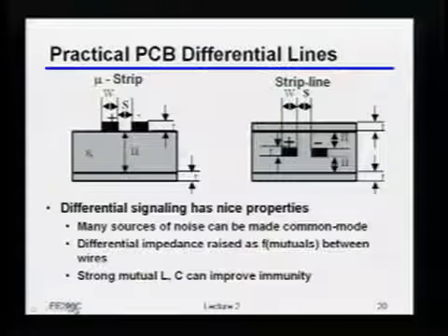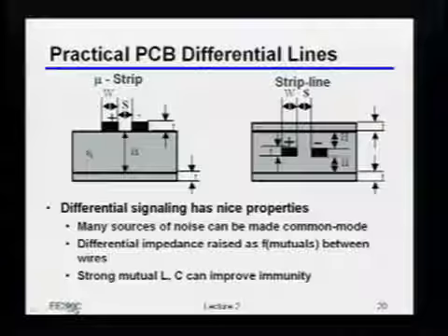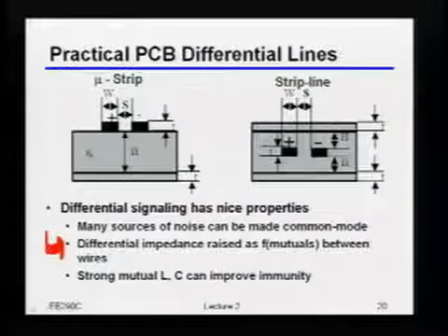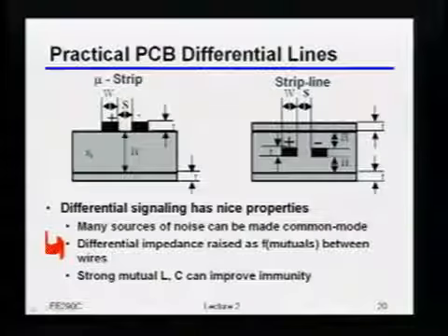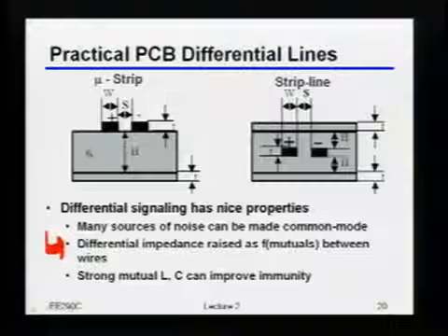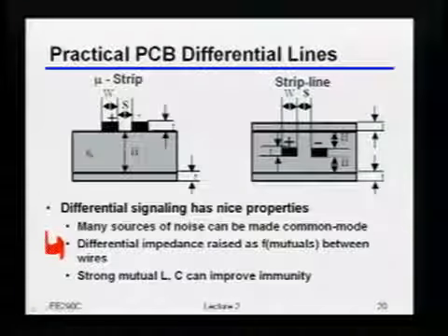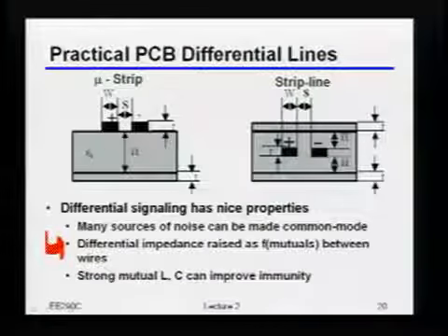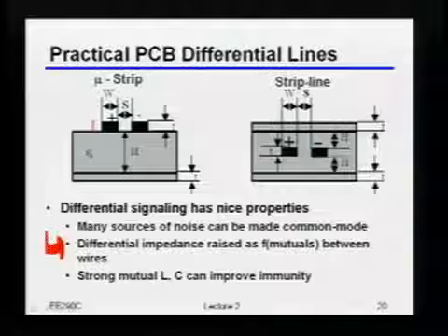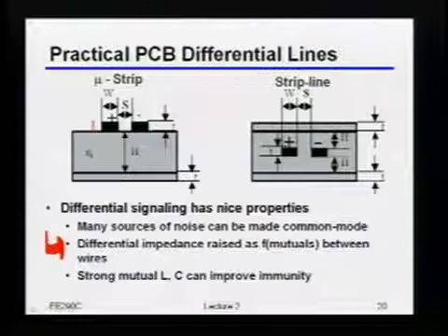But really, the point that I want to highlight here is to just remember: the only thing that makes things really, quote-unquote, differential is that you have strong mutual coupling between the two lines that you actually want to be differential, and less coupling between them and the rest of the world. Okay? So in essence, what you really have to do is control the spacing of the differential signals compared to anything else out there that you're interested in.